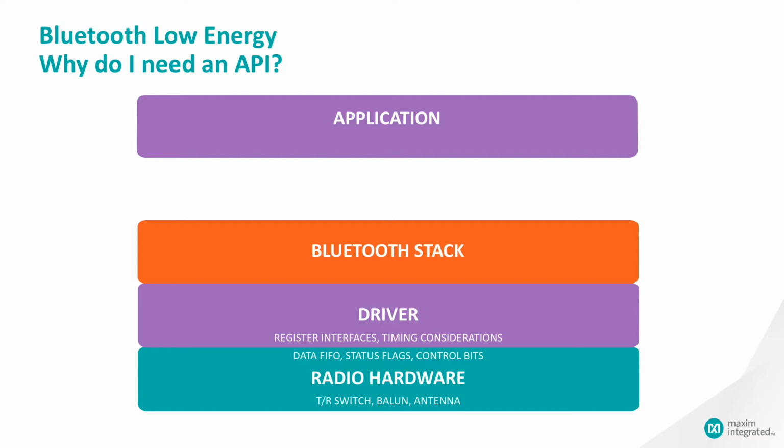Then the driver exposes a standard interface defined by common specifications up to the Bluetooth stack. The stack can then use a standardized status and control mechanism to manage the radio hardware without actually knowing all the particulars of the hardware itself. You could say that the hardware is abstracted by the driver.